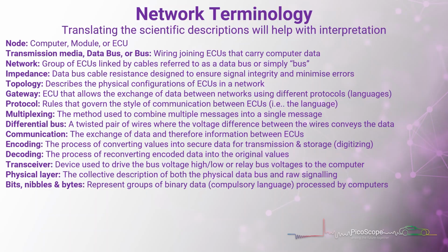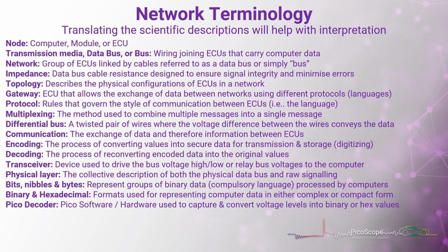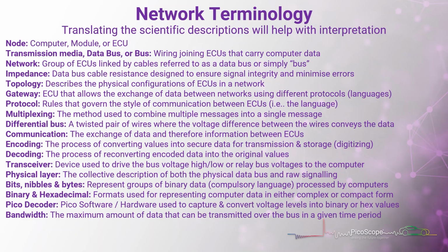Bits, nibbles and bytes represent groups of binary data, the compulsory language processed by the computer. So whilst we may not like it, we've got to know it. It's part and parcel of everything we're going to work with. Binary and hex are formats used for representing computer data in either complex or compact form. The Pico decoder, that's within PicoScope 7 software and the hardware. That's how we capture and convert voltage levels into binary or hex values.